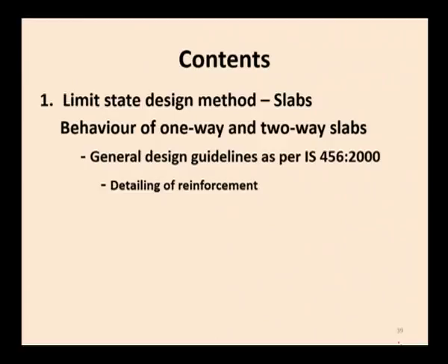In this lecture, here also we are going to see in detail the arrangement of reinforcement for one-way slab, two-way slab as well as one-way continuous slab. This is one-way simply supported slab, two-way simply supported or two-way restrained slabs, and also one-way continuous slab. And how do we provide the reinforcement detailing for these slabs? The reinforcement detailing is normally based on the behavior of the slab when it is subjected to forces.